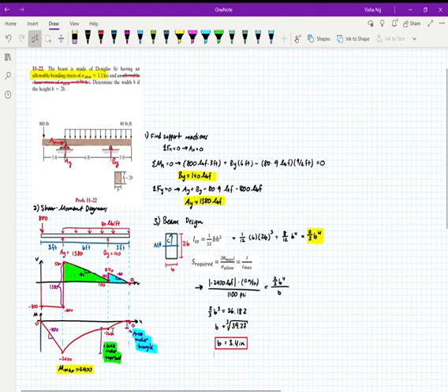From negative 360, I will increase to 0, and I can check that again. My displacement from negative 360 to 0 is the area under this triangle. So you can verify that you start at 0, you end at 0, based on the areas under this trapezoid and this triangle. So from my moment diagram, I can tell that M max is negative 2400. I'm going to take that value and plug it into my beam design.